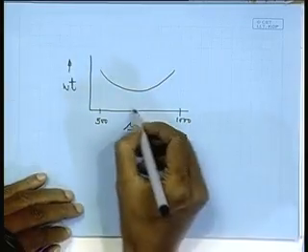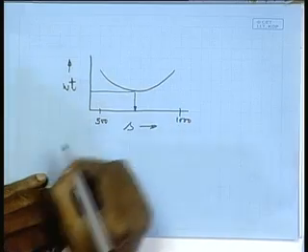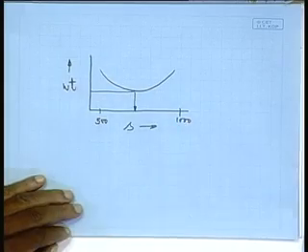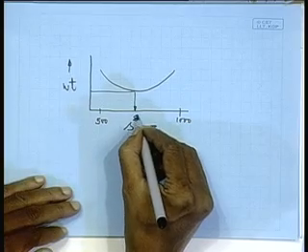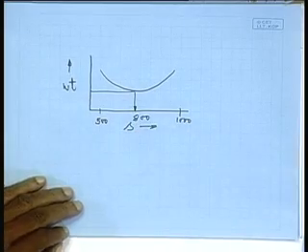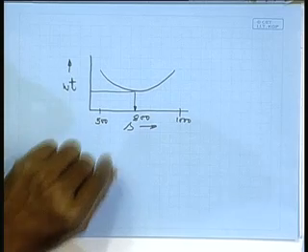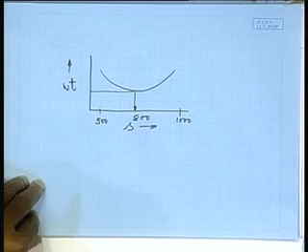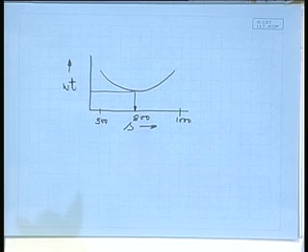So somewhere in the middle is my better value. That could be, say, I do not know, 800. So the logical way would have been to find the frame spacing wherein you have the minimum weight of the structure for the same strength.